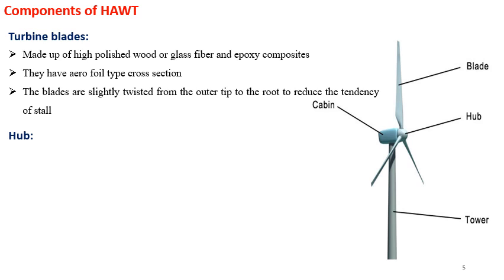So turbines with 3 blades have been used in several wind energy conversion systems, as we will see later. They are used in order to avoid the vibration experienced with 2 bladed rotors. These vibrations are related to the turning, that means yawing, of the rotor in order to face it into the wind.